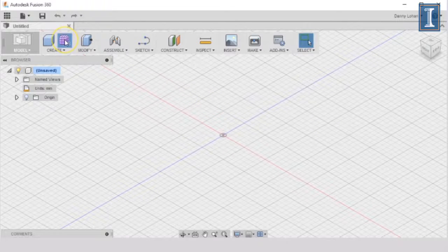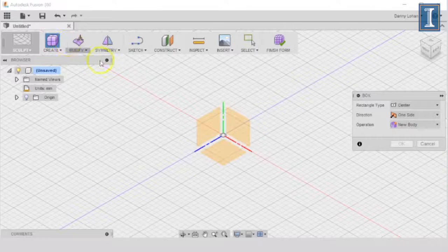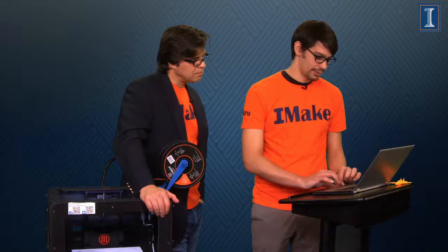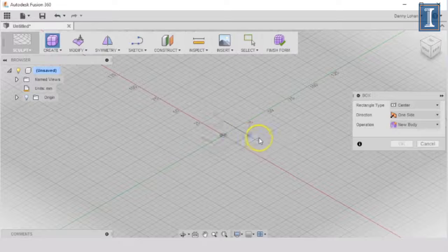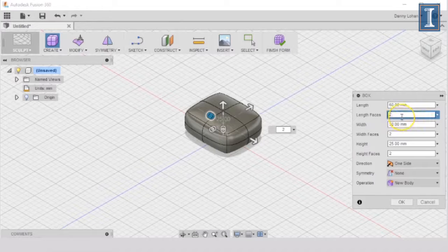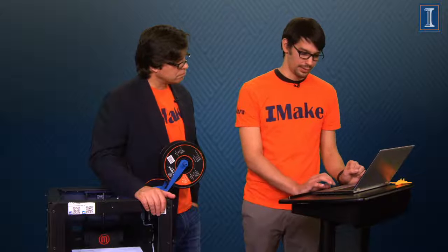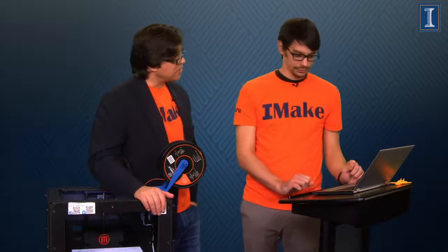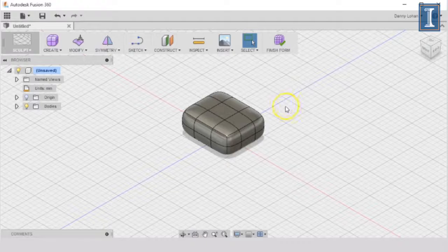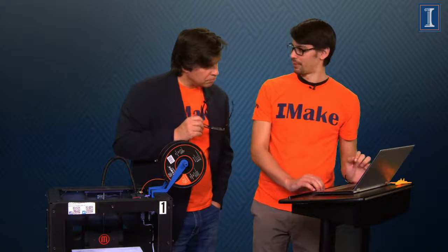If we create this, this tool, we enter the form environment. And in the form environment, we can input objects and modify those, basically free form. So here we have an object. One thing you would need to do is define how many faces and edges are in this part. So you can do that with the dialog box presented. And what's a face and what's an edge? So an edge is represented by the line, and 4 lines connected together usually represent a face.